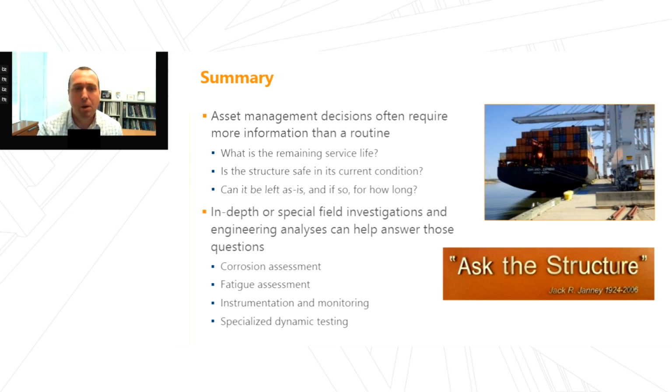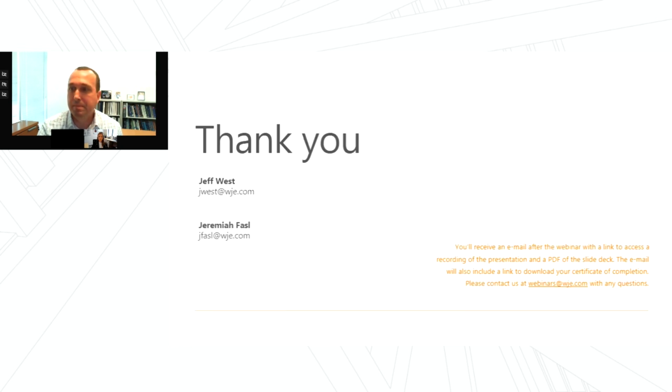And we provided multiple examples of doing in-depth or special field investigations, or combined with engineering analyses, whether that was a corrosion assessment, a fatigue assessment, instrumenting the shiploader, instrumenting the wharf, or dynamic testing. We're essentially asking the structure the current condition and then using those engineering analyses to evaluate it for its remaining service life. And with that, I will pass it back off to Liz.